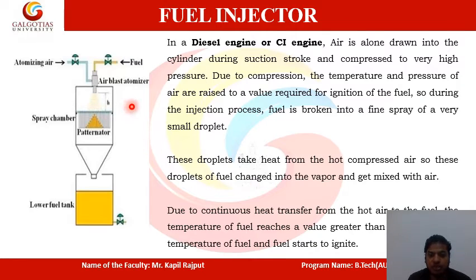Fuel injector. As the spark plug is used in the petrol engine, the fuel injector is used in the diesel engine to inject the fuel. In a diesel engine, or CI engine, compression ignition engine, air alone is drawn into the cylinder. I already informed you, only air is drawn into the cylinder during the suction stroke and compressed to very high pressure. Due to compression, the temperature and the pressure of air are raised to a value required for ignition of